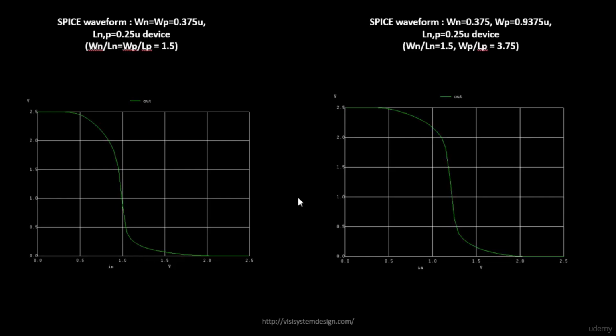There are certain parameters that will define the robustness of the CMOS, but this says that whenever your input is 0, this is your V in, whenever your V in is 0, your output is high. Whenever your V in is high, your output is low. This characteristic is maintained across all kinds and all sizes of CMOS inverter. So CMOS as a circuit itself is a very robust device, and that's why CMOS logic is the one that is widely used for any logic gate designing.